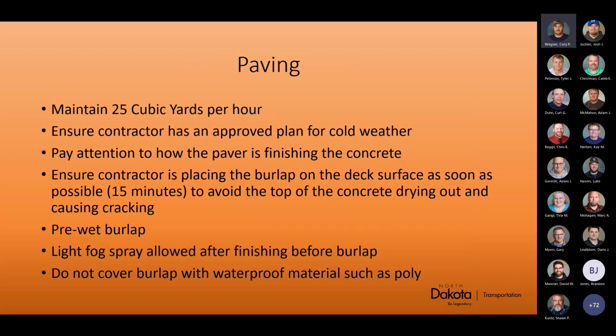Make sure your contractor's placing their burlap on that deck surface as soon as possible. Spec book says 15 minutes after the final finishing operation, to avoid the top of the concrete drying out and cracking. Make sure you pre-wet your burlap. They can use a light fog spray to allow finishing before the burlap is placed. But as with all concrete and all contractors, they like to try to bless it with a brush.